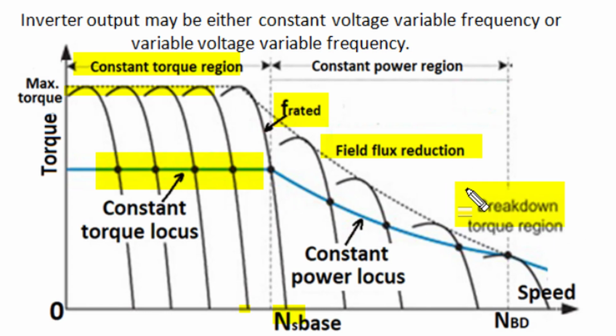If our torque reduces in magnitude with increased speed, as in machining tool operations like lathe, turning or shearing, where increased speed requires a lesser amount of torque, then this method is very convenient, and with reduction in load torque at increased speed, we can have different operating conditions with increase of frequency. And this operation where increased speed reduces motoring torque is also known as the constant power region of speed control.